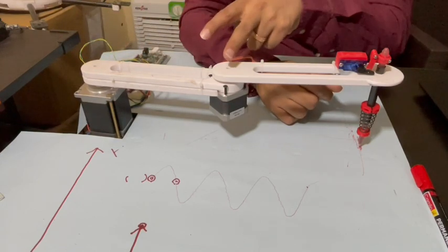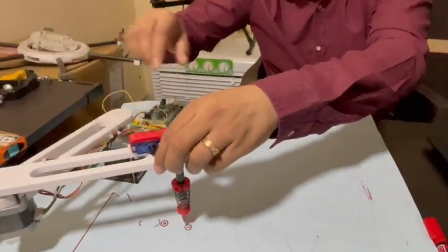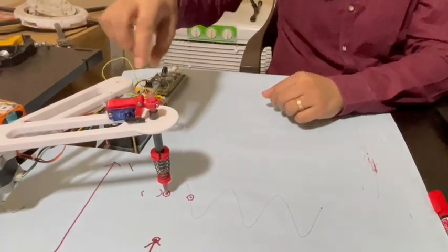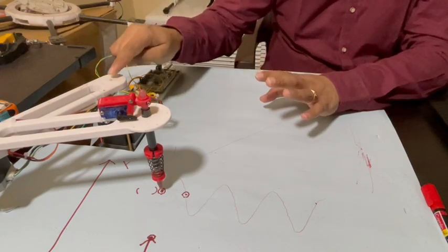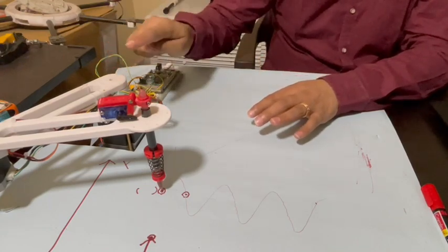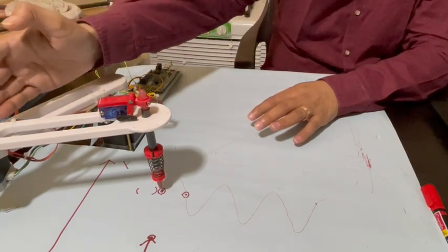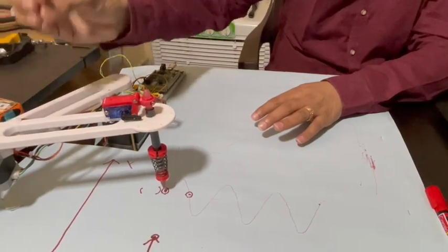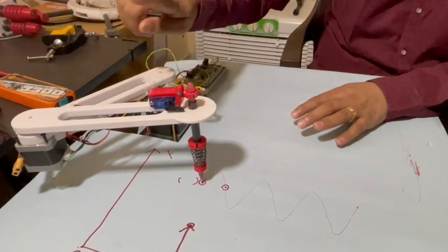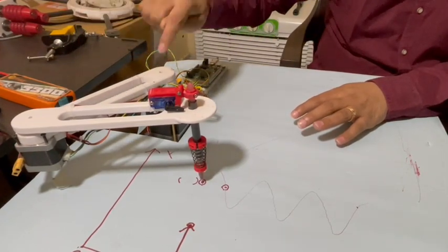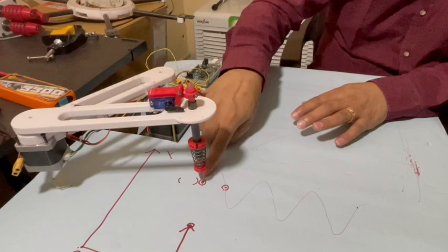See, joint 1 and joint 2. For each point, suppose that this is point number 1, you can see for this particular point there is a special configuration of the robot. This joint can have only a single angle theta 1, and for joint 2 there is only a single angle theta 2. By moving joint 1 and joint 2 to that particular angle theta 1 and theta 2, it will precisely go to point 1.